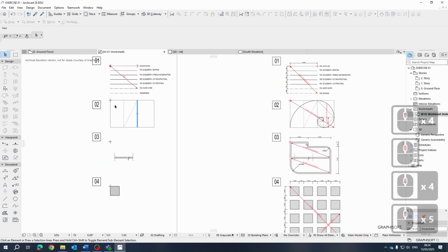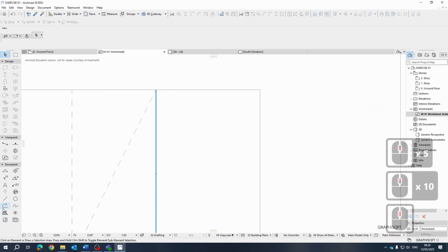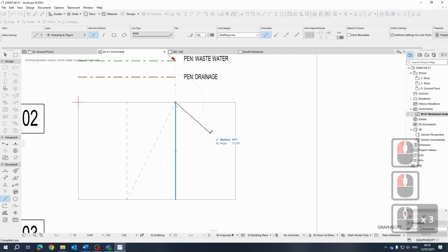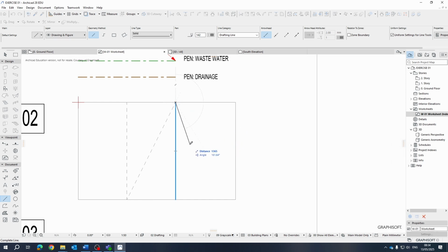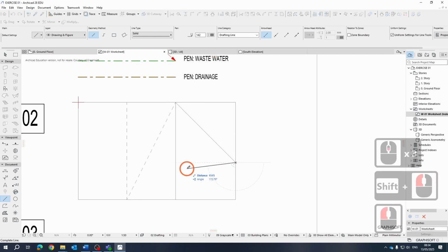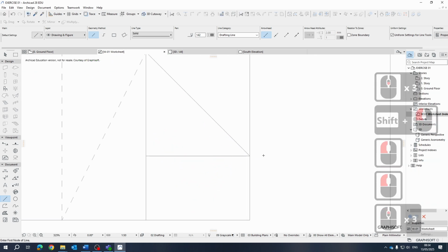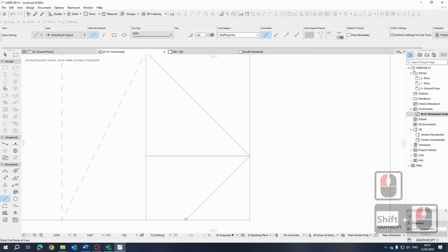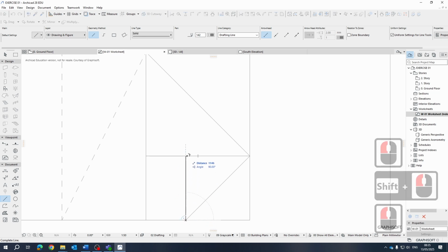Now, once you start drawing, to make this work correctly, you're going to need to work with a series of lines. So use the line tool and I'm going to select this intersection. Now at a 45 degree angle, so we need to snap at 45 degrees. Sometimes 135, you can hold Shift down and you can see it'll snap there. I'm going to draw the line back. So we're going to draw this back. Good. So I'm going to keep going. From that side, I want 135. Snap an intersection. I'm going to draw a line up again.